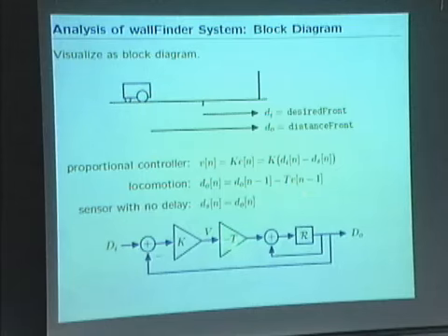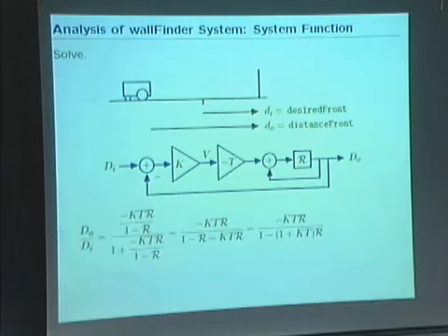And then we put the t in with a gain here, so I guess this part here is the plant. Okay, here's our simple controller, k, and our sensor is perfect. So that's our block diagram. We've just turned our robot into a block diagram, and we know everything about how to analyze those things, right?